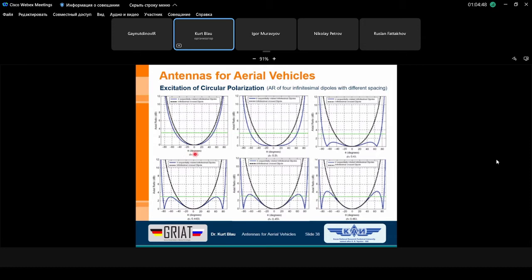And if we have this distance between the two pairs, the pairs of dipoles have the same distance, it's clear, they are only perpendicular to each other. Then we find out that our so-called axial ratio, meaning we want to achieve a perfect circular polarization, the axial ratio in dB should be, in the perfect case, 0 in log scale, because in linear scale the axial ratio is 1, major axis divided by minor axis, it's 1, and the logarithm is 0.